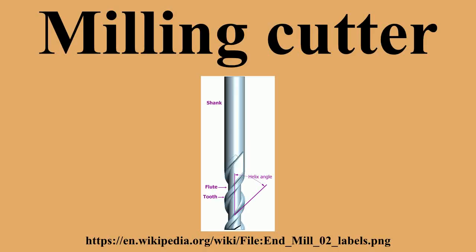Two reasons for that: for the maker, it is more practical to make the individual pieces as separate endeavors than to machine all the features in relation to each other while the whole unit is integrated, and the user can change some pieces while keeping other pieces the same. One arbor can serve for various shells at different times. Thus, 5 different milling cutters may require only $100 worth of arbor cost, rather than $500, as long as the workflow of the shop does not require them all to be set up simultaneously.